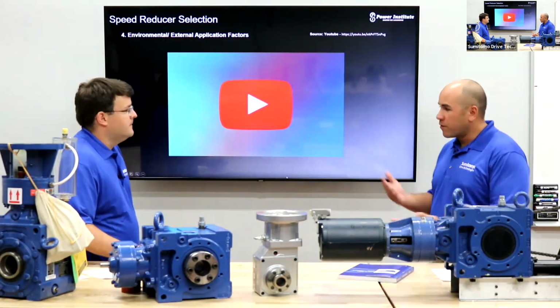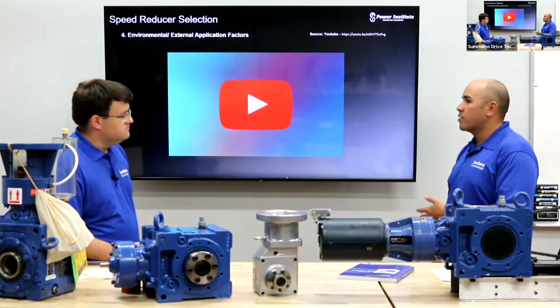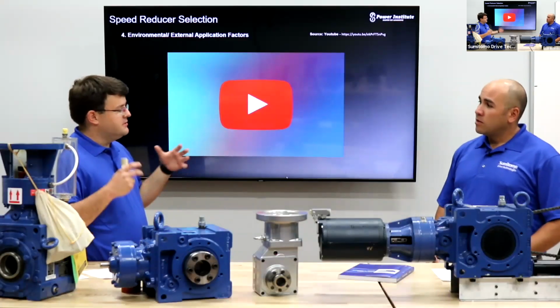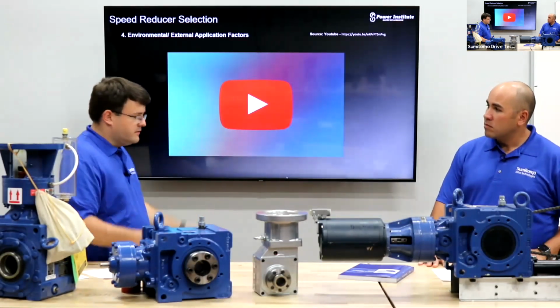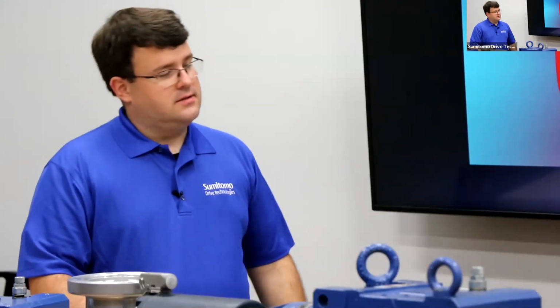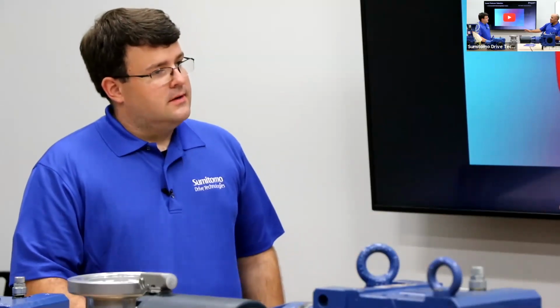Okay, so we've got a couple different things, right? We've got the service class, service factor, duty cycle, and then our environmental and external applications. So once we know all of those things, we're ready to select. You fully understand what the application is doing. You have a good understanding of where it is in the country or the world, wherever the case may be. And now you can go ahead and make the selection on the gearbox. So I think we've got a good selection problem here.